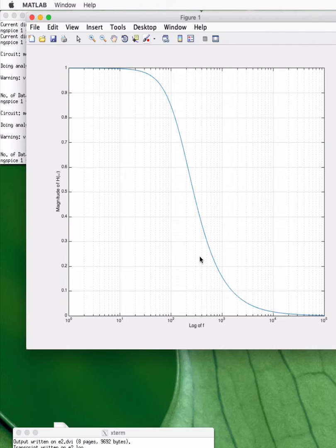And this is really, again, highlighting the advantage of working with both SPICE and MATLAB, because if we make a mistake with our circuit analysis, that mistake is going to continue on to our MATLAB plot, because we're just going to plot essentially the equation that we came up with from our analysis. But SPICE is a completely different thing. It doesn't ask for our equations. It's not interested. It just wants the topology of our circuit. And so it's really useful to use SPICE as a check to make sure that our analysis is correct.